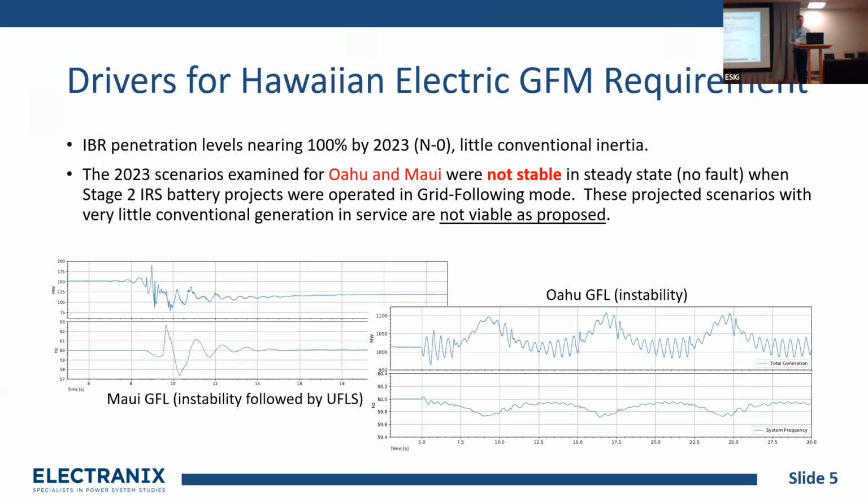So the first one, you heard a very nice presentation from Deepak this morning. Thanks for presenting all of that detail, Deepak. This is really the steady state small signal that he referred to in the first presentations. In Hawaii, we studied everything in as much detail as we could, with huge PSCAD models, and studied the scenario with no grid forming. It doesn't work. This isn't a real surprise to anybody, but we showed it again in the Hawaiian system. You can't just do that. It won't be stable in a small signal sense, goes unstable, and is not viable.